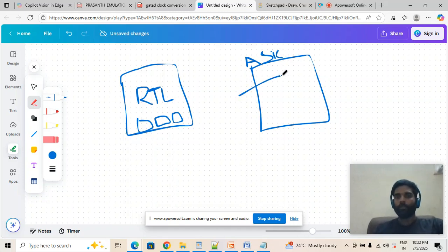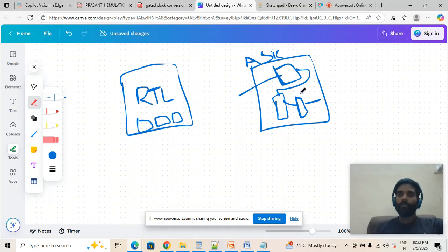I write some custom logic here, and I need some dedicated block. For example, I want to do some signal processing operation. I can use some IPs which are already available in the tool itself, in the library itself. So I connect my custom logic to the IP, and somehow it connects like this. These are IPs, for example an asynchronous IP or any signal processing IP you want to use. It's a common way, right? You don't want to develop RTL for everything.